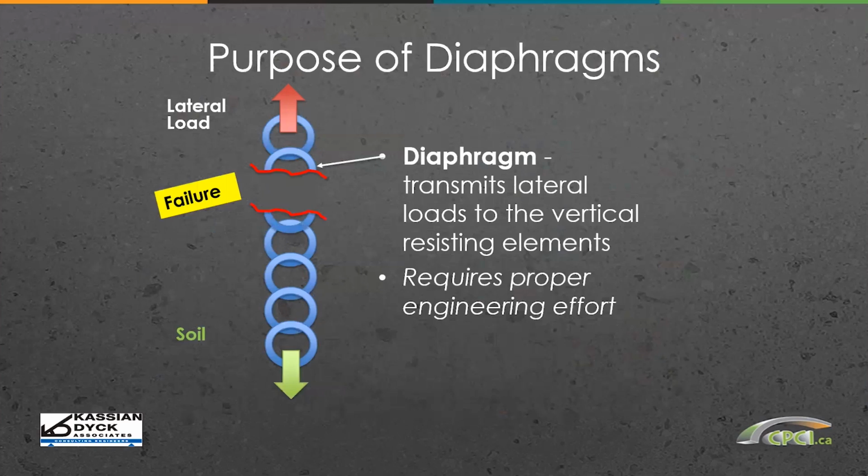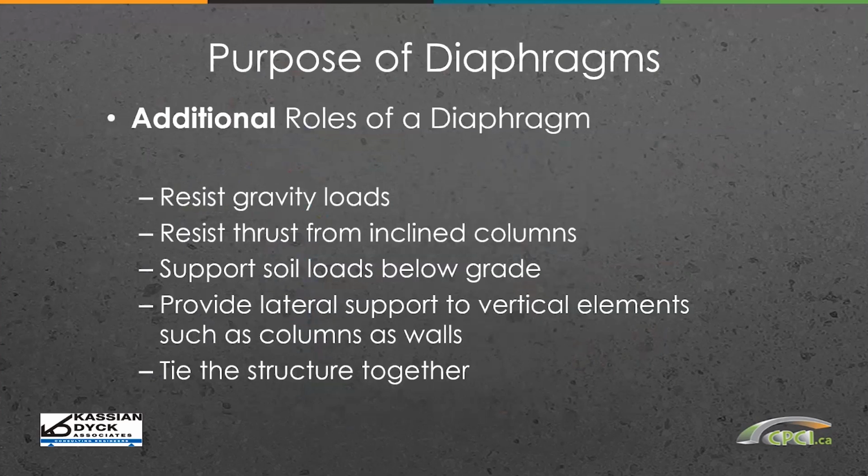If we don't properly look at the diaphragm or the diaphragm connections, then our load path could be broken, and as structural engineers, it's our duty to follow the loads through from where they're applied down to the final reaction to ensure that we have a complete load path for the safety of the structure, and that requires proper engineering effort. Additionally, diaphragms resist gravity loads.